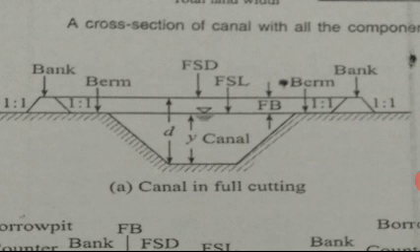Berm is necessary to provide a space for widening the canal if necessary. Berm is necessary to protect the bank from sliding down towards the canal, and berm is necessary to deposit the silt to make an impervious lining, etc.